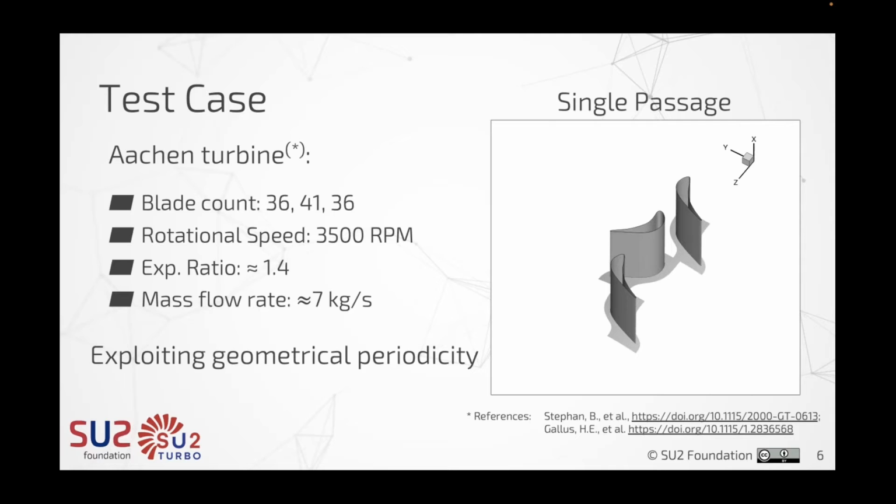If you're running a calculation for a case that has different blade count for stator and rotor, and you're using a mixing plane interface between stator and rotor, it doesn't matter, because the pitch is just stretched when the information is passed from one side to the other.